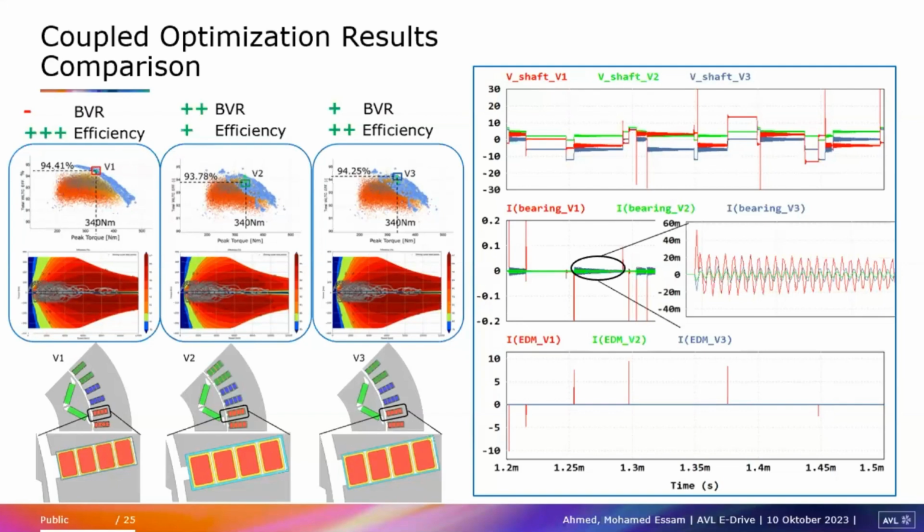I have been in contact, and maybe here I open the ticket again for forces, about the electrical field analysis having a transient or time domain solution. Currently it is frequency dependent, but we have been trying to replicate some end-of-line insulation tests with such methodology, to check, as you mentioned, the breakdown voltage, partial discharge and so on.